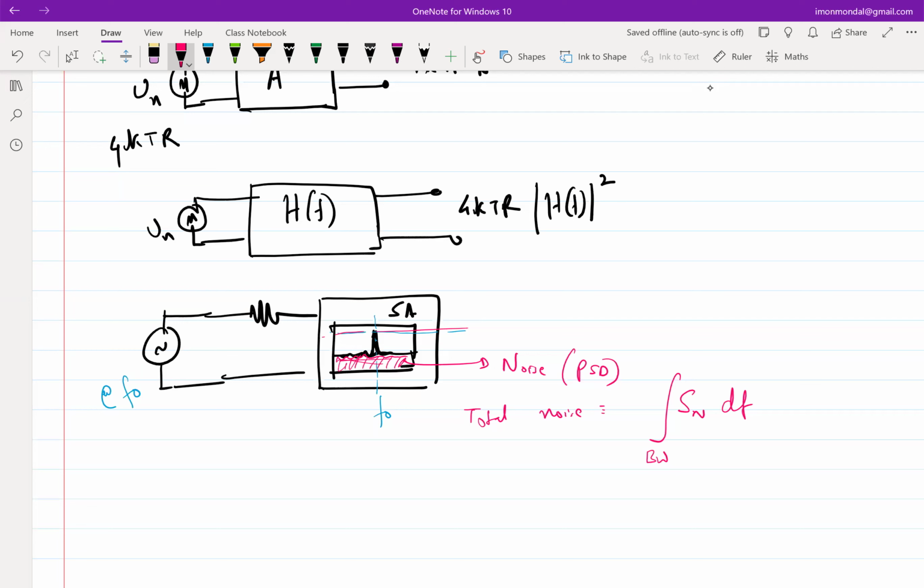So, if I send a tone of only 1 kilohertz and do not do anything to the rest of the 1 megahertz, I'm inviting noise from that 1 megahertz channel, but my signal is only at some tone around 1 kilohertz. So that obviously is not a good thing. If you don't have anything else to send, then instead of sending only a 1 kilohertz tone at one particular frequency, I will send 1 kilohertz tones at multiple frequencies.